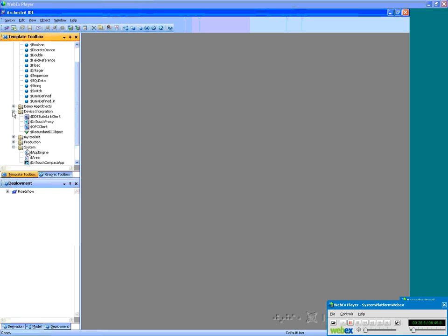We also have templates, hopefully you can see under System, which are used to model the plant. We have engines, which are used to run objects. We have areas, which are used for alarm areas. And we also have InTouch templates. We also have device integration objects. We have other objects that you can download and load into the system, which will give you connectivity to the major PLCs like Allen Bradley and Siemens. If you're using a third-party OPC server, we also have an OPC connectivity object, and an InTouch proxy object to allow you to connect to InTouch applications to use that as the source of your data. There are some other objects available as well for connecting to things like iFix to use that as the source of data, and there are a few others.